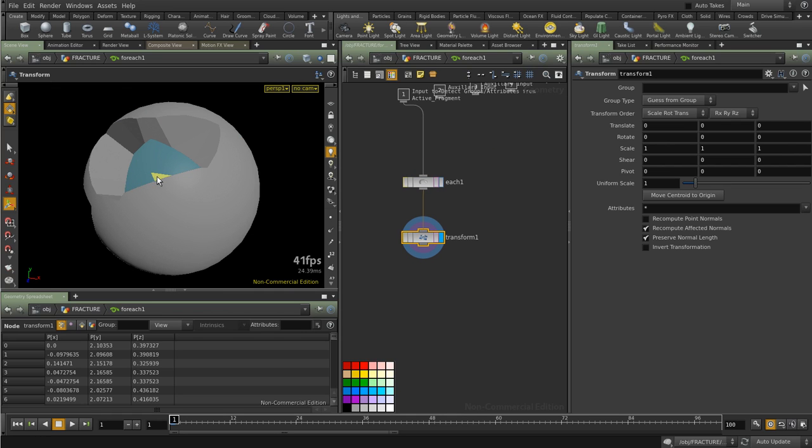To do that I need to create a little expression. The expression is called Centroid Expression. To do that I can select my pivot, my x, y, and z, and for my x a dollar sign CA, the centroid by x.